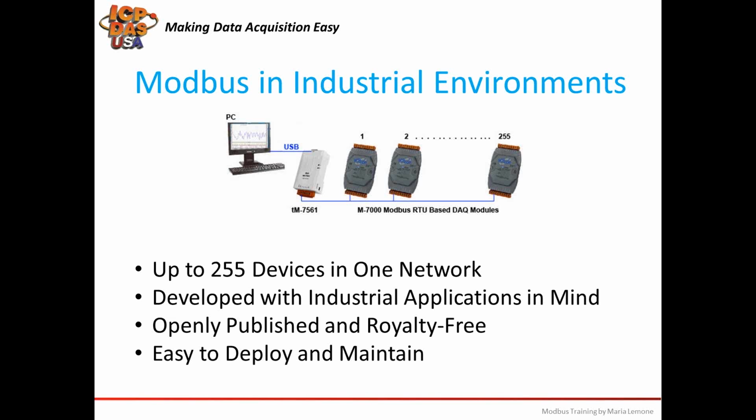If you do have Wi-Fi networks at the same location as Zigbee devices, since they do operate over the same 2.4 gigahertz band, you may want to use a different wireless method like RF modems for the communication to go on a different wireless frequency. That way the communication won't have any traffic.